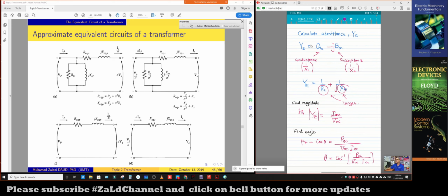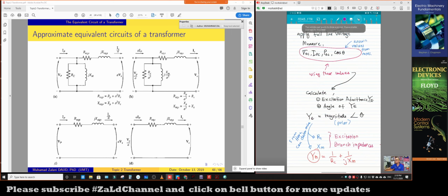So basically, first thing, let me repeat from the beginning: we do the open circuit test. These are the values we get from the experiment. We do the measurement using metering equipment. We let the transformer be open circuit, put the probes, then measure the voltage, current and power at full line voltage.